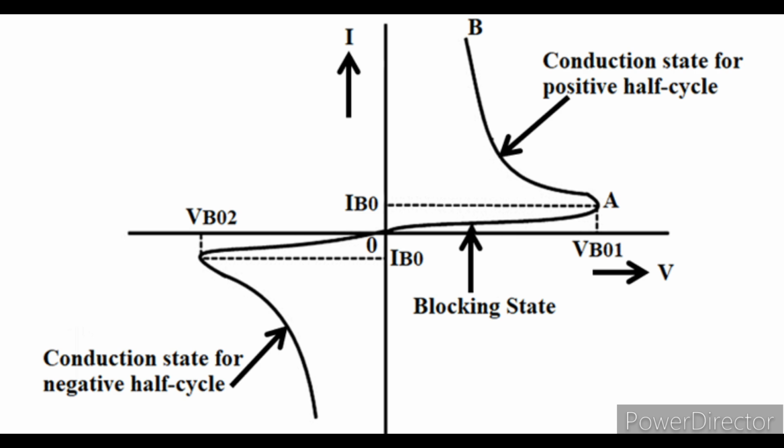Till now, we have studied the DIAC, thinking of its application as a switch, because switching needs proper control. But DIAC cannot be used as a switch. Because there is no gate terminal for the DIAC, we cannot say when the DIAC will get turned on when it crosses the breakover voltage, and so we can't predict when the DIAC will get triggered.